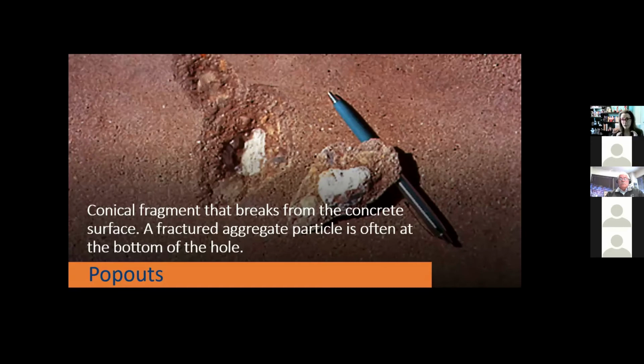Here's one thing you can do. You can downsize your top size of your aggregate for these when you have these concerns. And that means that you're lowering the pressure buildup by having lower size, top size aggregate. But while you do that, you're changing the mixture. You're then upping the paste content, which may or may not be ideal for you. And it then changes your thermal control. It changes your shrinkage. It changes all sorts of things in your design. But there are things we can do to minimize pop-outs. And it really is about your surface finish. Doing something like an exposed aggregate finish definitely helps you with that, but it might not be ideal for all structures. So pop-outs are a nemesis in our industry.